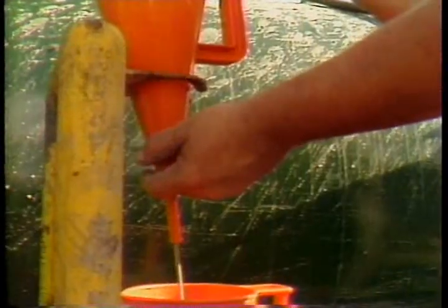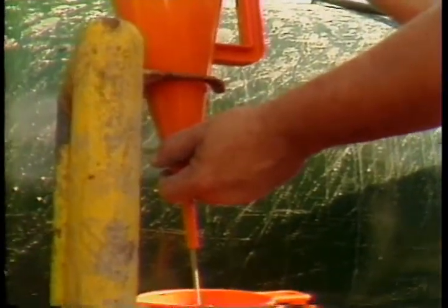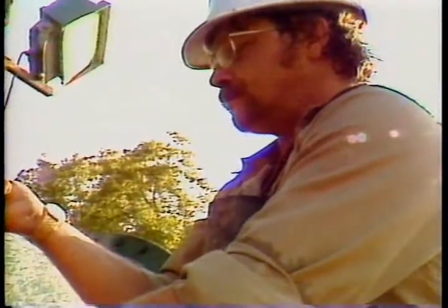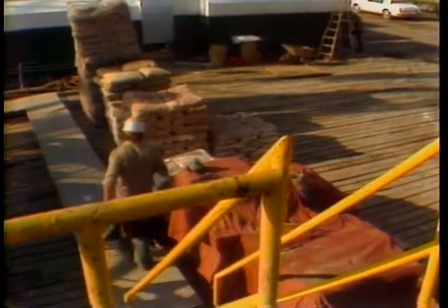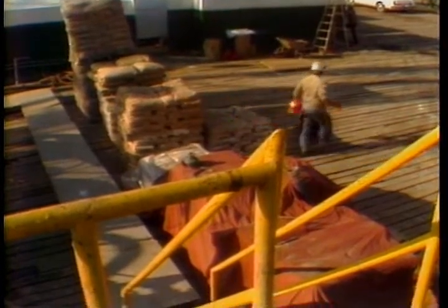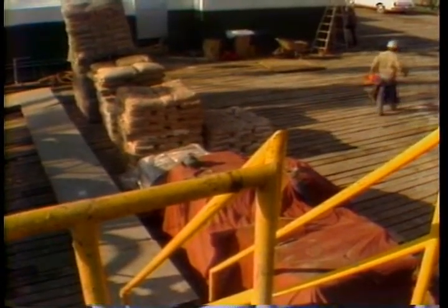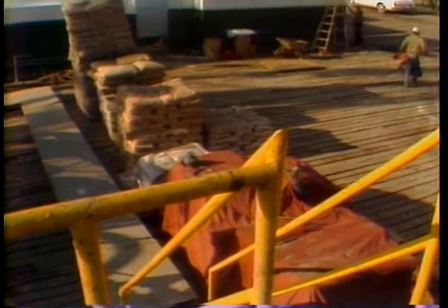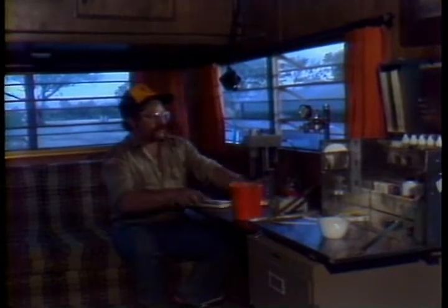You remember a few minutes ago I said that this test isn't very accurate? Well, let's take a look at how the mud engineer gets an accurate viscosity reading. He starts with a sample of mud that is delivered by you. You know, earlier we told you that you should always take your samples from the exact same place. Well, the mud engineer needs the same thing for all his tests. And he'll need it to be in his cabin for testing within 5 minutes so that his readings reflect the qualities of the mud at the drilling temperatures. So keep this in mind.